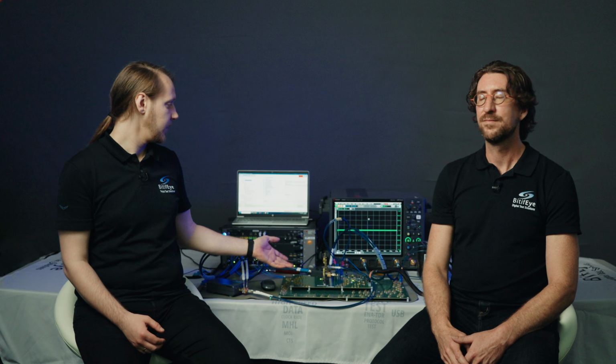Sure. The back channel contains all elements starting at the DUT up to the BERT receiver. That includes obvious parts like the PCB traces, connectors, cables, and redrivers if present. But also things like bonding wires inside the DUT and BERT, as well as the FFE and the ADC inside the BERT. To get the lowest bit error rate in the back channel, it's crucial to adjust all parts together for the given setup. The DUT must send the best preset, the redriver must be set correctly, the FFE taps need to be adjusted, and the sampling setup consisting of sampling delay, input range, and threshold has to be fine-tuned.